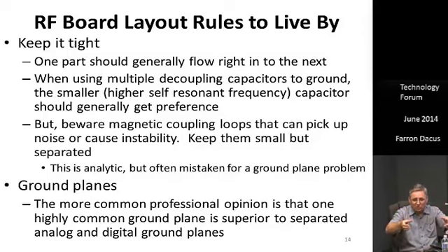Well, these current loops are generating magnetic field, which comes up off the board. Like if the surface of this table is the board, it's coming up off the board, looping around and coming back in, according to Faraday's law. And that magnetic field comes through the other loop. And there is a coupling coefficient between them. It's usually pretty small, but even if it's 0.001, when you're looking for 100 plus dB of isolation, it becomes almost a shorting factor. Energy goes through it, and you see the switching noise in the linear regulator output.